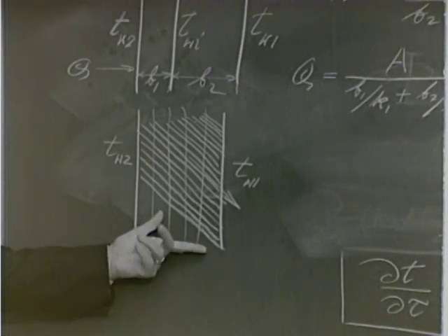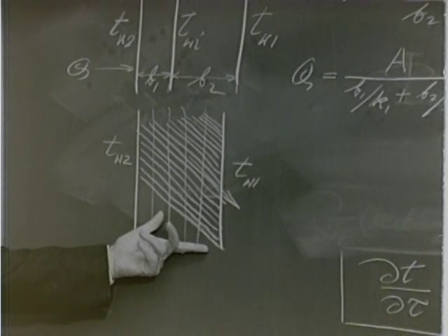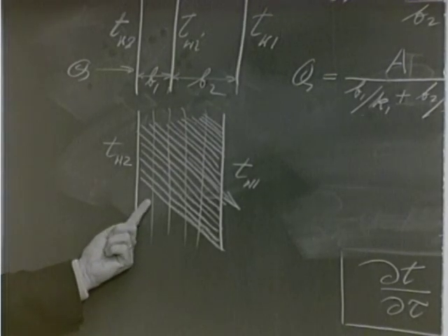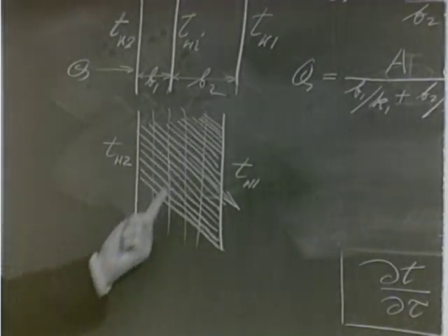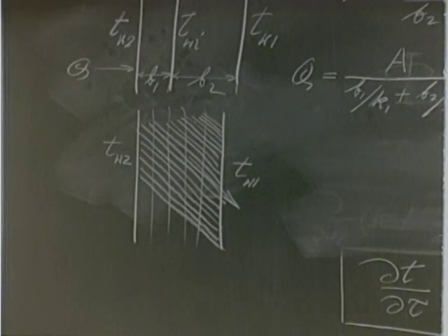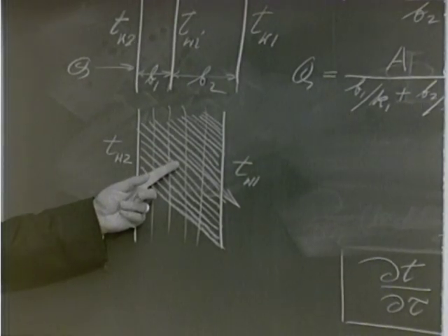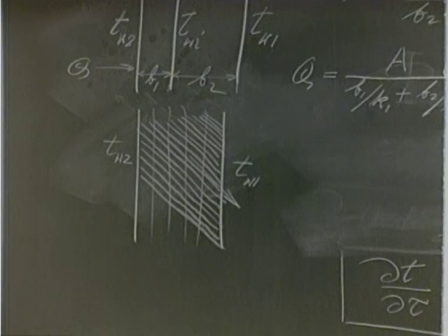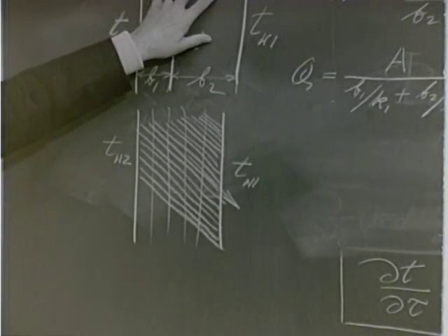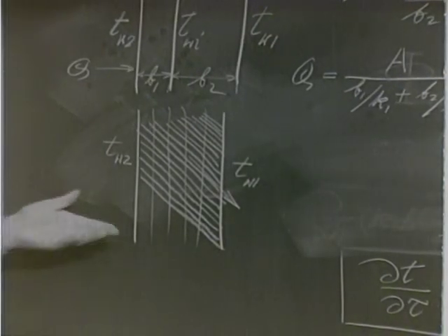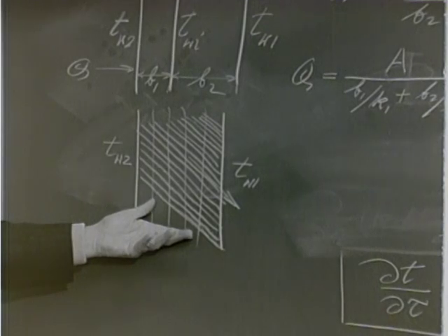And this is the case in any kind of material where the thermal conductivity is different in different directions. Here, of course, the thermal conductivity in the direction normal to the layers is 0, because there are always layers which have no heat conductivity. So we have here an example of a material which, as we say, is anisotropic: it has conductivity in one direction different from the conductivity in the other direction. Whereas before we have always considered isotropic material, where the thermal conductivity is completely independent of direction. Now we have quite some materials which are of this nature.